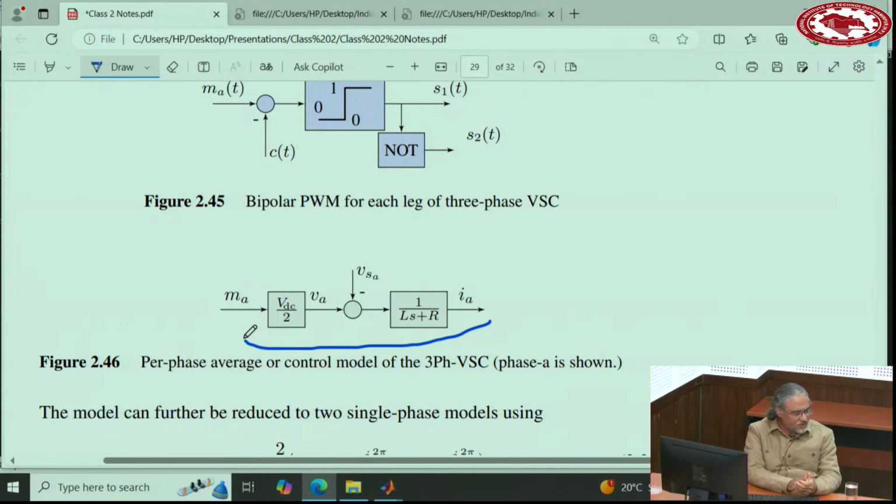However, under these assumptions that we made, VA plus VB plus VC equals 0, basically we do not have practically three independent circuits. We only have two independent circuits. So for that reason, it's not necessary to work with three. We can work with two. And that's the concept of a stationary domain or alpha beta domain. So alpha beta domain converts ABC to alpha and beta. And it says, I don't need all three, A and B and C. Let me only derive two, alpha and beta.